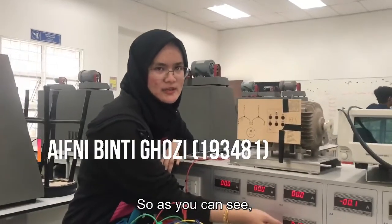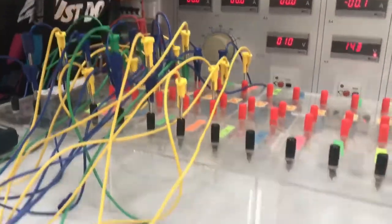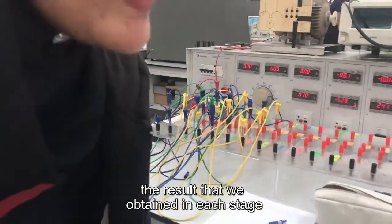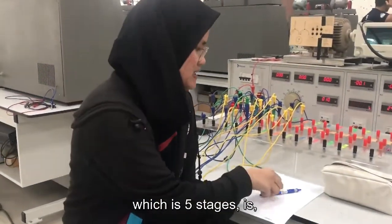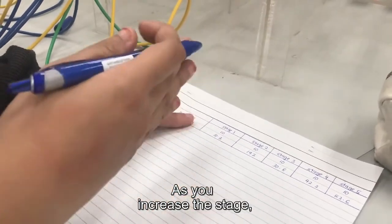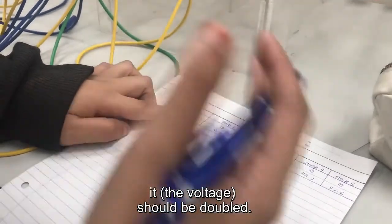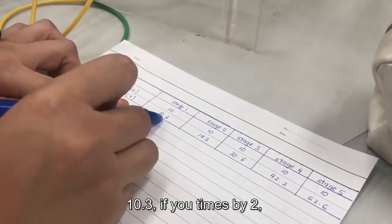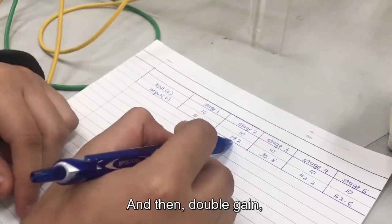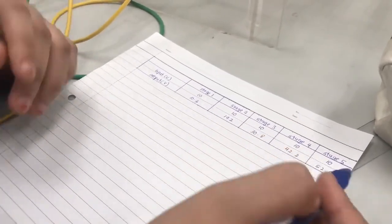Okay, so as you can see, we have set the AC voltage input to 10 volt, and then the output will be DC voltage. The result that we obtain in each of the 5 stages is, in the first stage, 10.3 volt, and then as you increase the stage, theoretically it should double. So for example, this 10.3, if you multiply by 2, it will be 20. So this is 19.2, which is acceptable, and then double again, and then we get 30.8, and then 40.2, 52.6. That is our result.